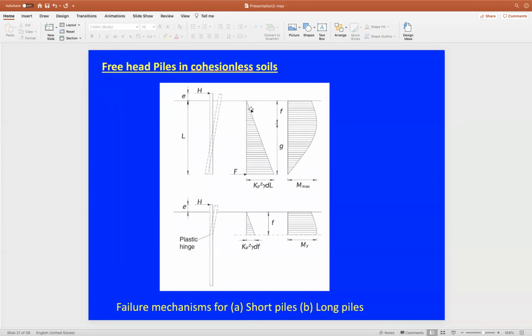But if you take the sum of moments at the upper part and the lower part together, that will cancel the moment at this point, because that will be 0. But you need to hinge this point to make this point fixed, and to consider only the upper part above this point, above the maximum moment point, or below the maximum moment point. So you can either work out the value of G and the value of F, or you can work out the value of F and the value of H. We have already found the value of H from the previous step.